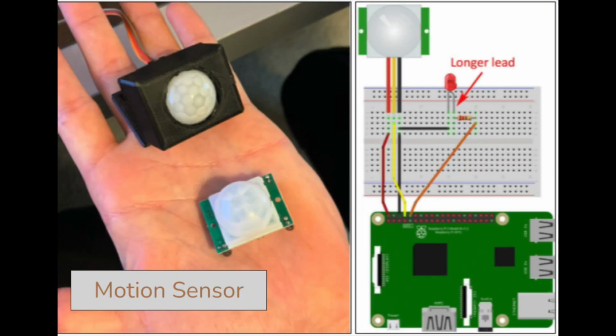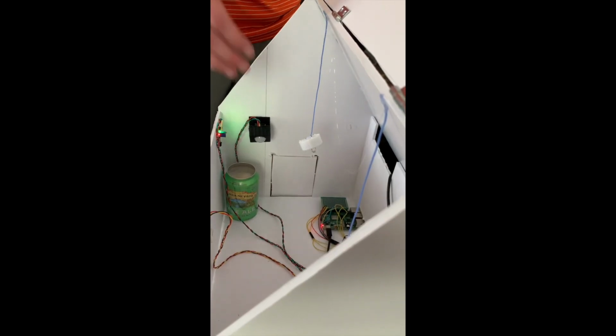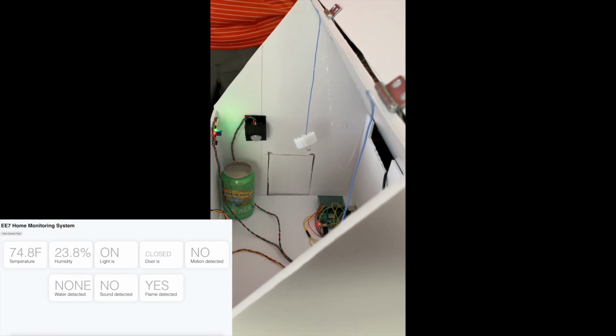The motion sensor detects motion in its pointed direction. For this project, the motion sensor detects the presence of someone entering the front door of the model home. This sensor involves using a pyroelectric crystal to detect moving heat signatures. We had the sensor configured to send a signal to the Raspberry Pi when motion was detected. The signal would turn off after a certain amount of time until motion was detected again.